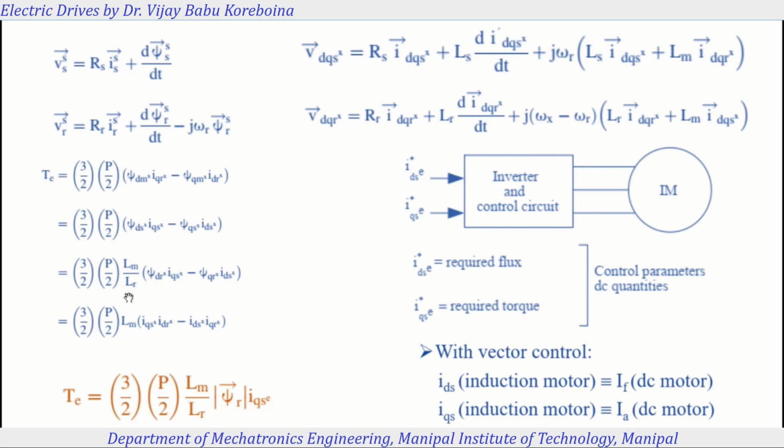Based on the magnetizing components, flux and the current IQS, this IQS, the quadrature component, controls the torque.